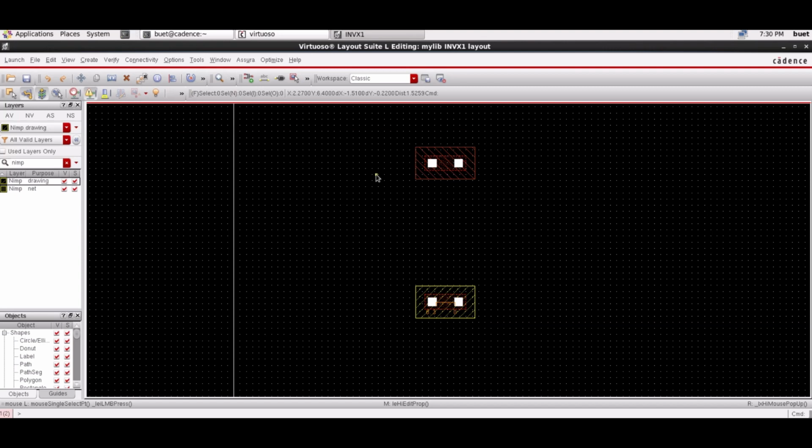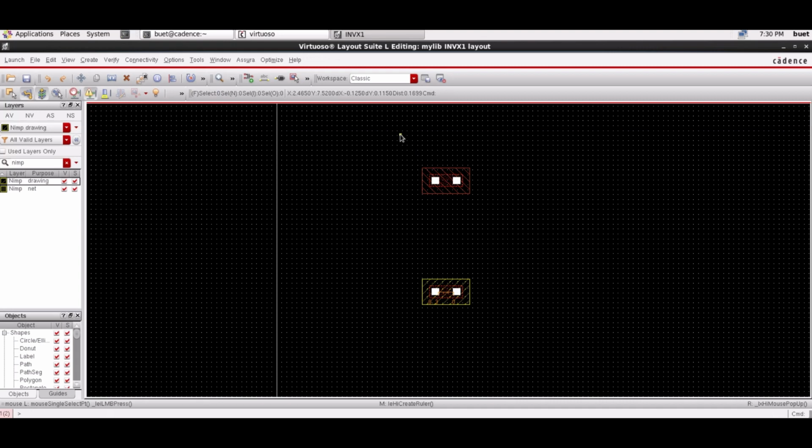Now, with more metal layers available in today's silicon process, using the routing approach, such as first metal traverse vertically and second metal traverse horizontally, would be advantageous in standard cell physical design. Using this method, the second layer or metal 2 can be used for power and ground routing over the internal standard cell transistors. In standard cell layout, it is preferable to use the first conducting layer, such as metal 1, as much as possible to make internal connections of NMOS and PMOS transistors.